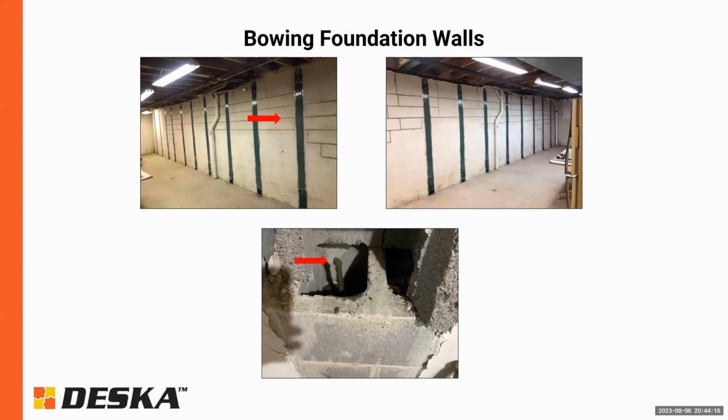Hey Brian, have you ever seen a carbon strap fail? Yes, I have. Typically, where they fail is in the substrate itself. If the substrate is not prepared properly, you have to grind the coating off, the paint coating or whatever stucco coating happens to be there, and then it needs to be vacuumed out.